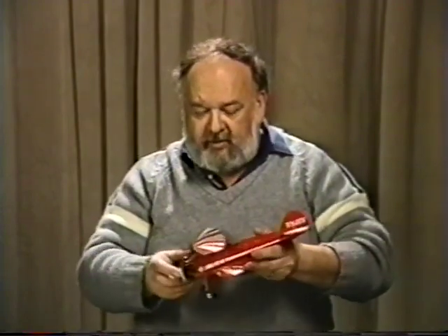Remember though, on longitudinal stability like this, you can increase the stability by moving the CG further forward. But as you move it further forward, your tail loads become higher, and so do your stick forces. Now to maneuver the airplane, to change that position, you have to move the stick a lot more and the forces go up much higher. If you move it back, your stability goes down, but your maneuvering capability increases because your stick forces have gone down.